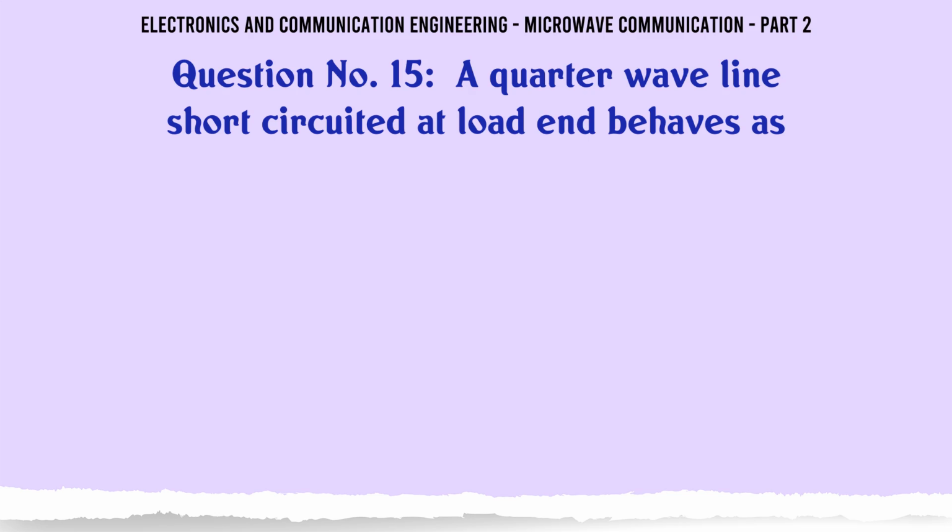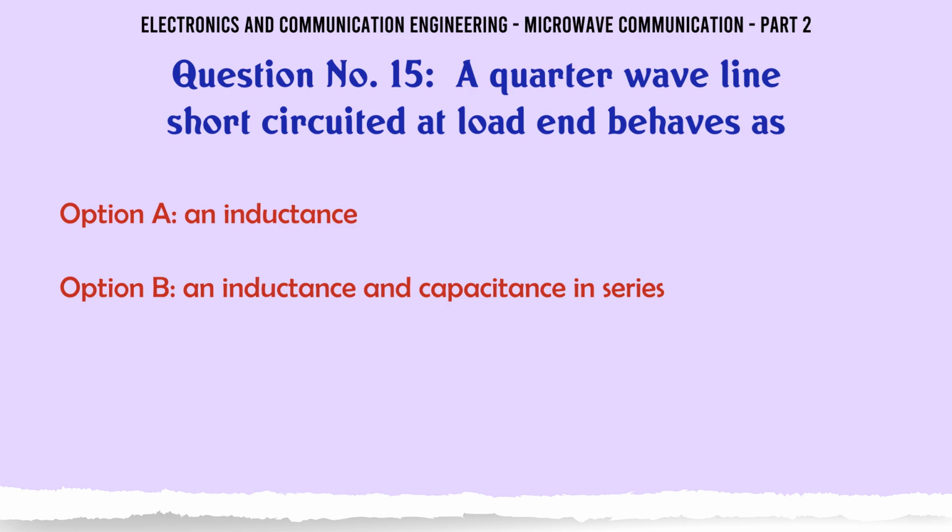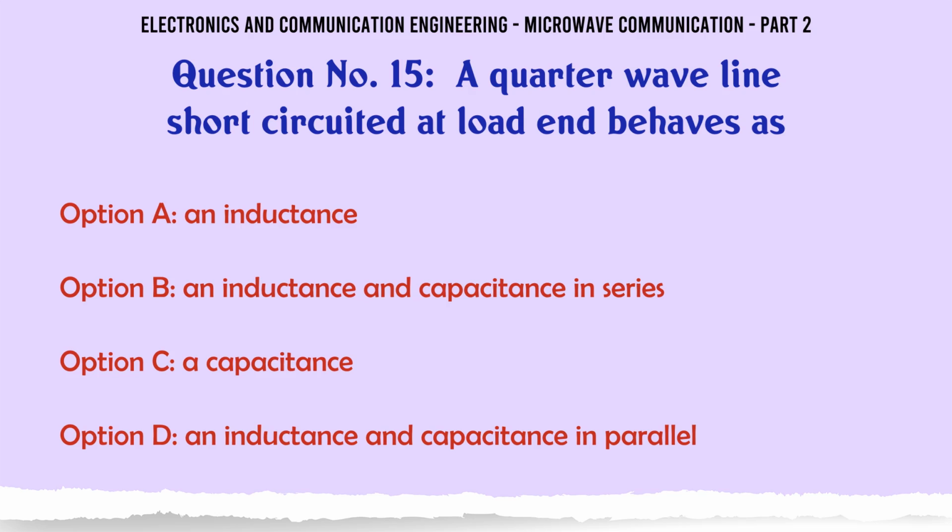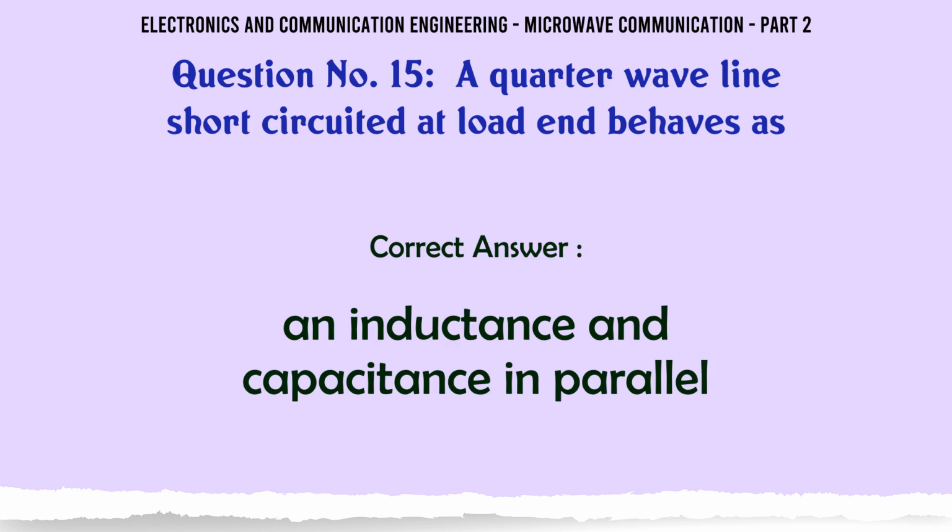A quarter wave line short-circuited at load end behaves as A: an inductance, B: an inductance and capacitance in series, C: a capacitance, D: an inductance and capacitance in parallel. The correct answer is an inductance and capacitance in parallel.